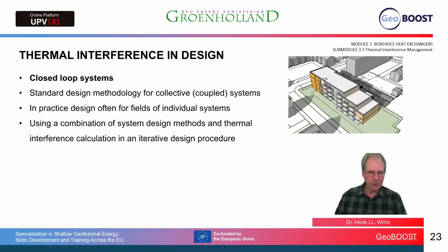So let's now take a look at thermal interference in design. For closed-loop systems, the standard design methodology for collective coupled systems is usually implemented, considering all the boreholes connected together in one large system, and also using only one particular configuration with one distance between the boreholes, all boreholes the same depth, and one energy profile with regard to heating, cooling, and domestic hot water.